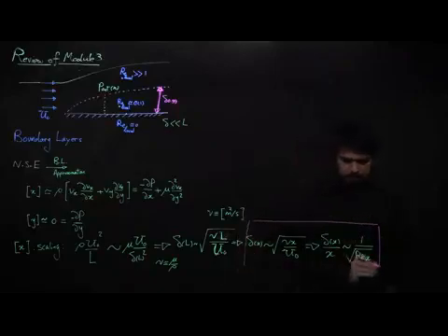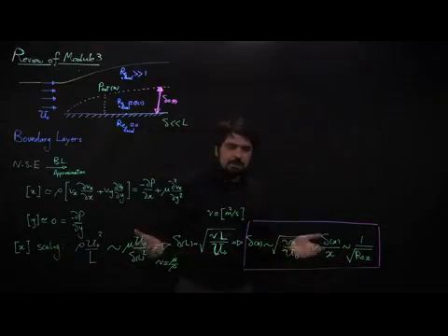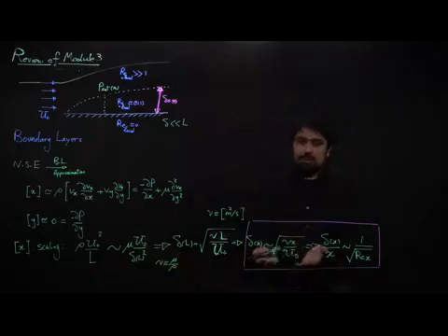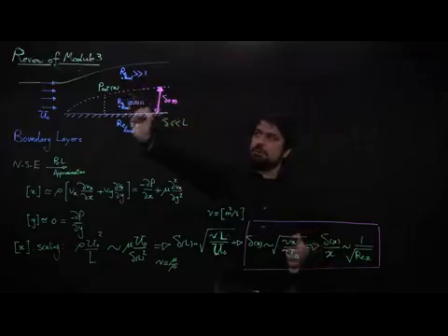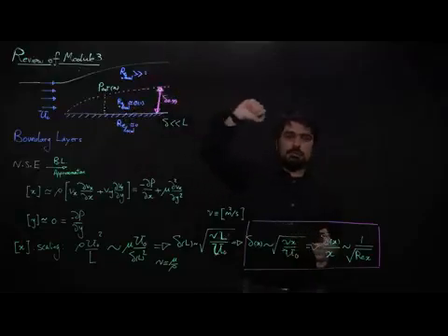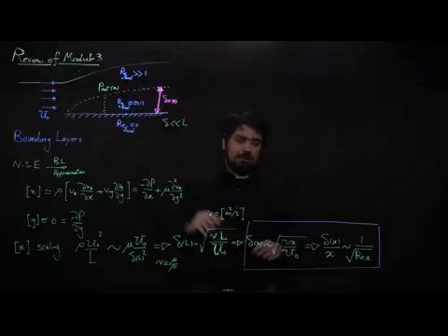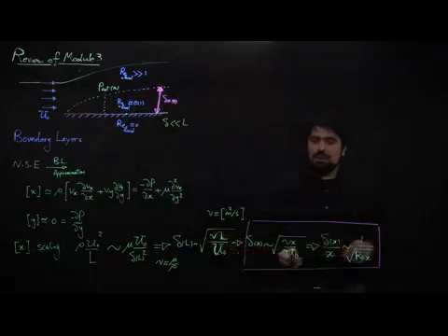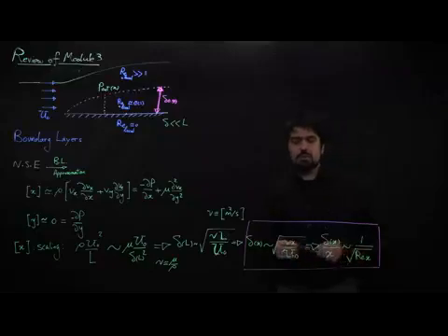The most important thing to keep in mind is the fact that we didn't do any solution, we didn't do any numerical integration. Just by scaling, we reached the conclusion that indeed, if we want to divide our problem into a region where viscous stresses are having the same scale as inertia, and a region where inertia terms are much larger than viscous stresses, the dividing line should actually be increasing with the x component, and it should increase with the x component in this manner that it goes as a square root of nu times x over u0.